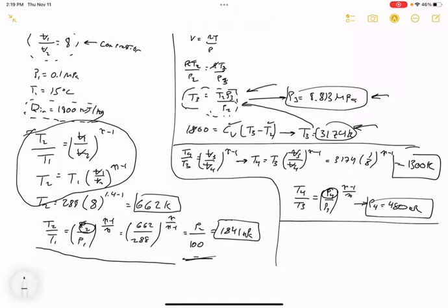But we don't like rejecting heat because it's kind of a waste, right? But we want to make sure that we're being as useful as we can be, in that if we put in 100 joules, we want to use up as much of that as we possibly can, right? Because everything we don't use is wasted as Q out. It's rejected later on. So thermal efficiency refers to how good we are at making use of Q in and turning it into work out.